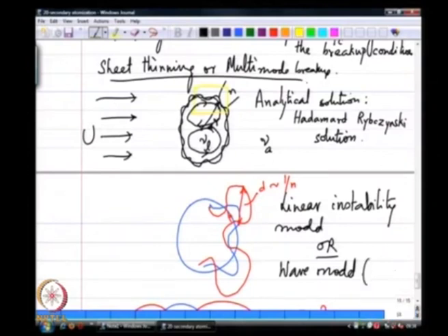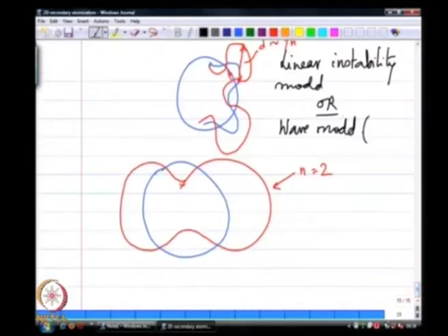This wave model assumes not a spherical drop, but a cylindrical drop. So, it looks at wave number in just one plane, assuming no waves in the other plane, and from that gets an m star which is responsible for the most unstable wave number.